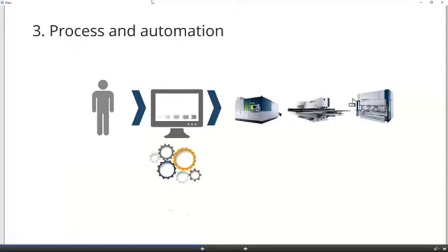And then automation was another big focus of ours as well. So we wanted to automate the software as much as we could and really wanted to focus on redundancy in the programmer's daily activities or tasks. Especially with things like preparing geometry, rather than opening parts one at a time and then saving them or cleaning them after, and then saving them as a DXF, we wanted to make it so you could batch import geometry and automatically clean multiple files at once.